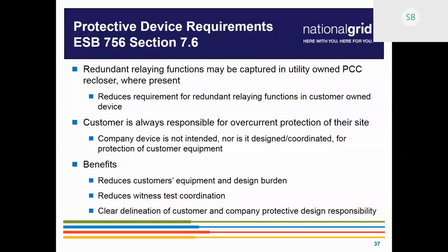where we're able to. So what that means for everybody here is that you don't always need a redundant relay, so you don't have to put in a relay-based protection for your project. What you do still need to have is overcurrent protection for your site. So we're moving that functionality to our recloser, but our recloser is in no way, shape, or form meant to protect your site. We're doing this with the explicit intent that we're protecting our equipment, our assets, and everything upstream is good.